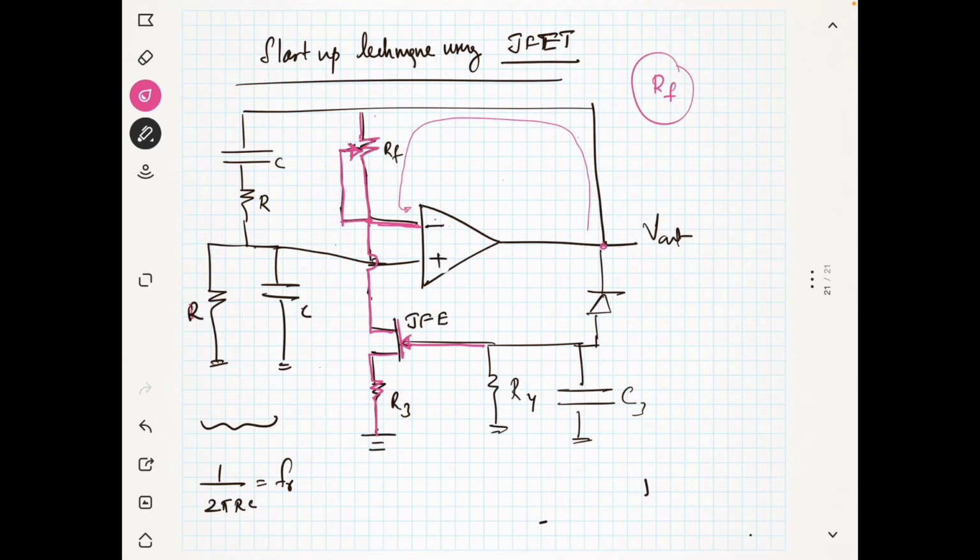Okay. Now what is the resistance at the input side? Because you need two resistors. One is RF and another is RI. And where is that RI in this picture? That's what I want to show you. That RI means this is the path to the ground. RI is actually going to the ground, right? Because here is the amplifier, minus and plus, and here is the feedback network, and this is the Wien bridge oscillator. So RF is there. Yes, you identified RF. Now where is RI? Instead of RI, you have a path to the ground.